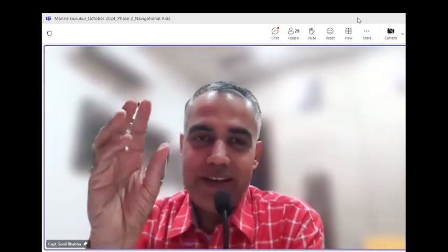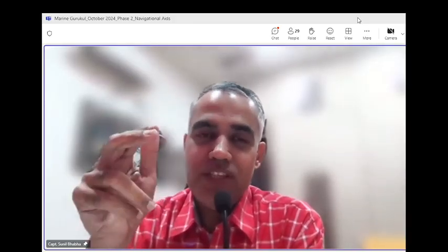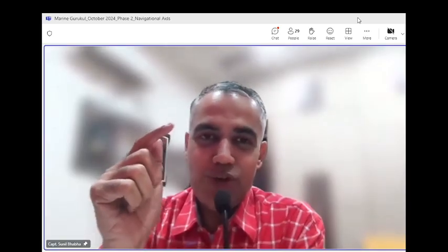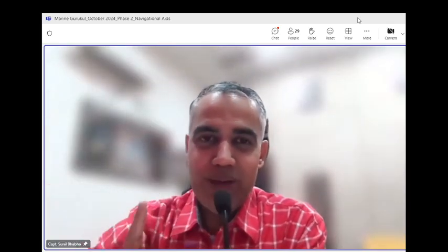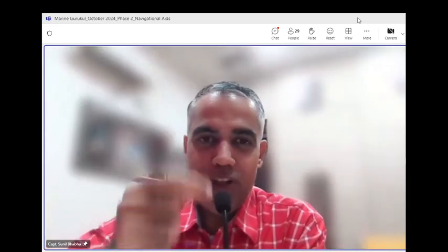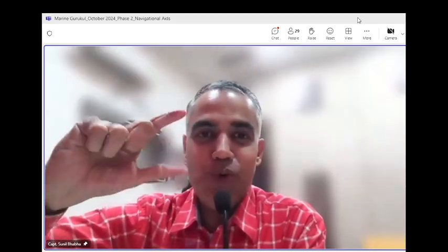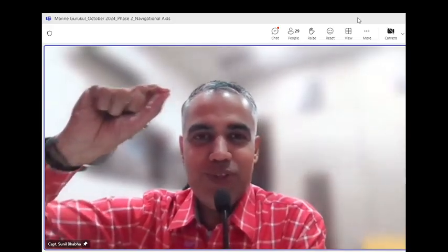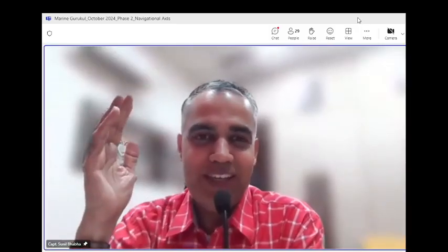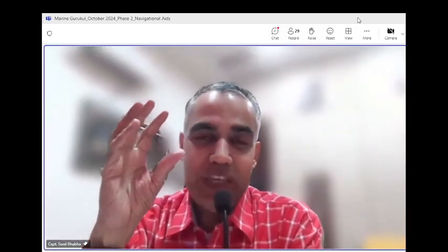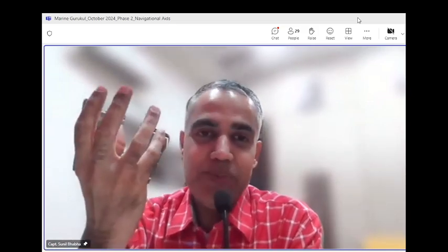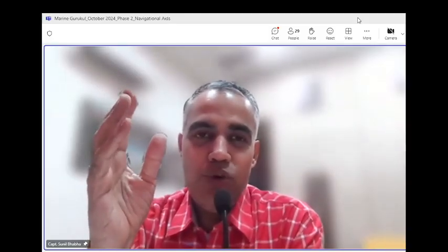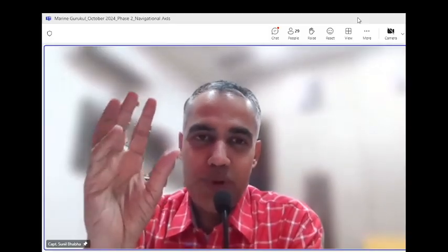If the compass is not well corrected and you change the hemisphere, the direction of the Earth's magnetic field changes. In the north hemisphere, the lines are going down. In the south hemisphere, the lines are coming up. So all the vertical structure will have their poles reversed. If the mast was having a blue pole on top, when you change the hemisphere you will have a red pole on top. This is the reason why the deviation may get disbalanced and your deviation card may be inappropriate. So the first reason: compass is not properly corrected.